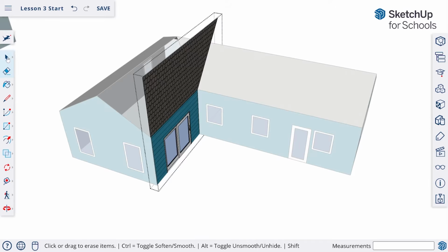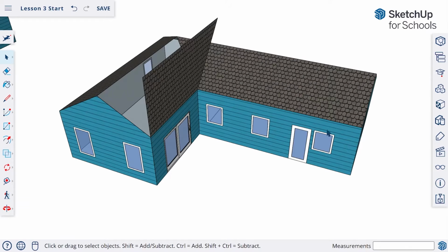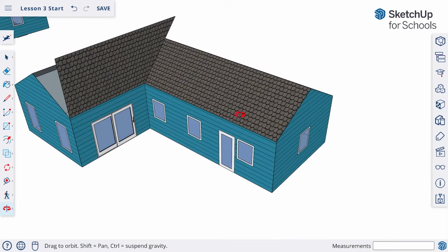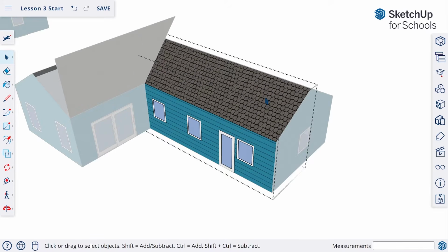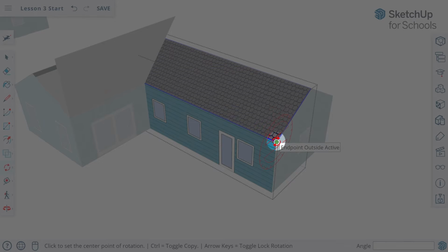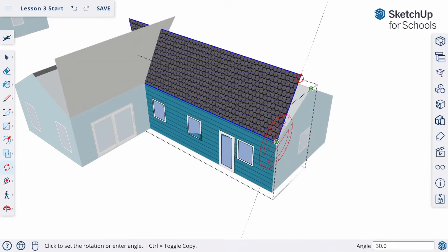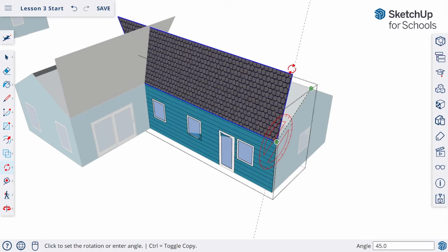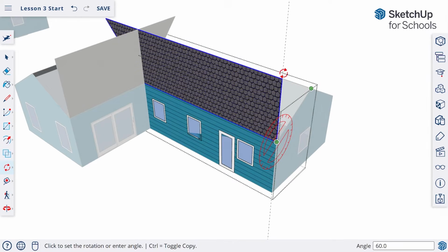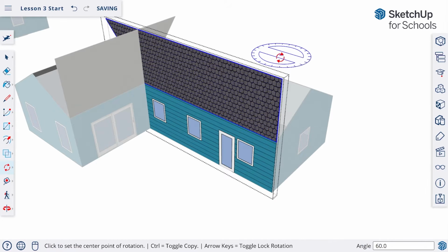Now let's repeat this for the other groups that have roofs in the model. So we'll take the select tool, we'll click outside of the group, we'll orbit around to this side here and double click inside of our third wall group. Double click on the roof surface with the select tool, click on the rotate tool, and then find not the green axis, but this time the red axis. Click and release at the center point here to start our rotation. Click again for our 0 reference and move our cursor up. Find that 60 degrees. You can also see my guideline of the rotation is actually aligning to the vertical wall as well. That's a good indication as well. Click to set it in place.